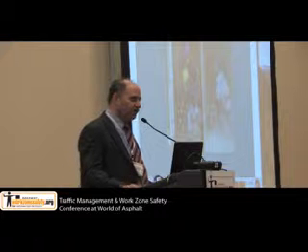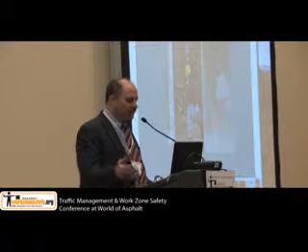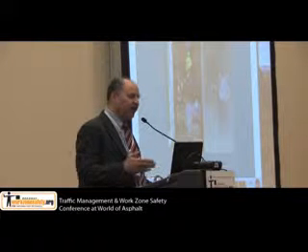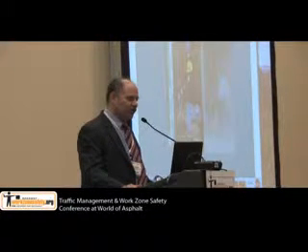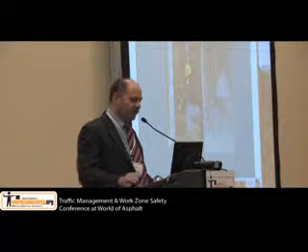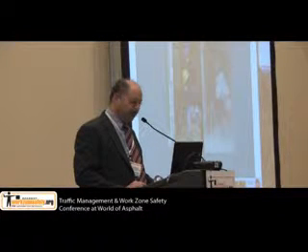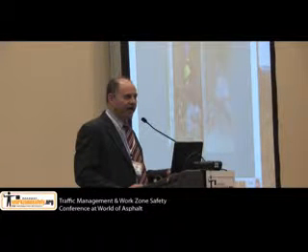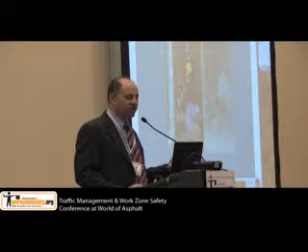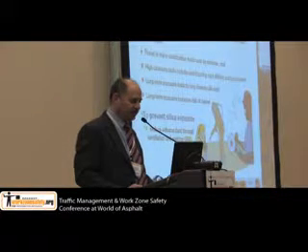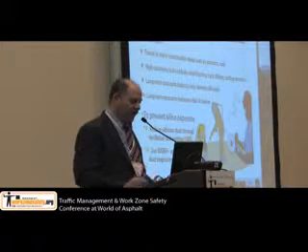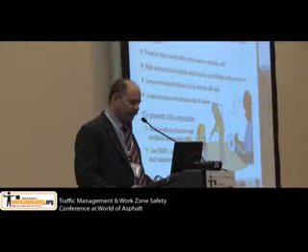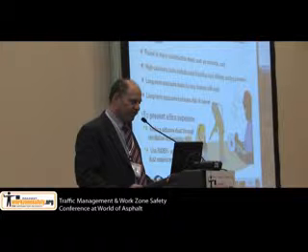And here's a demo we developed where you can see on the right side someone is cutting without using any water. On the left, they're wetting the saw as they're cutting. So you can see there's a huge difference in exposure. And it's likely that OSHA, when they come out with their rule sometime this year, is going to propose that all cutting has to be done with wet methods or with local exhaust ventilation. Or you need to use NIOSH-approved toxic dust respirators. And there's the OSHA standard.